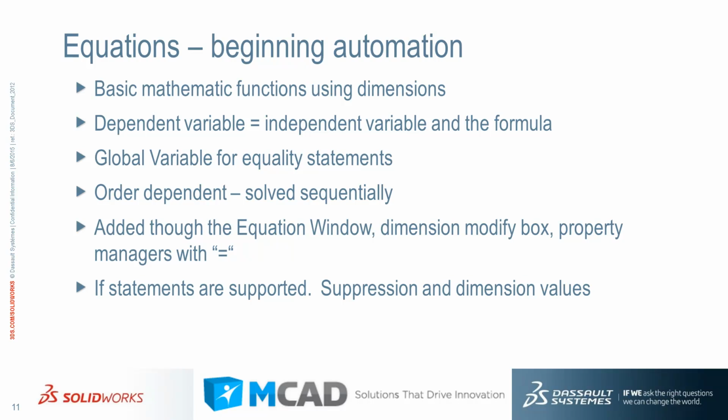And finally, if statements, Visual Basic if statements are supported. You can use them to drive suppressing a feature or different dimensional values a dimension is controlled by. So you can get some pretty interesting functions just using native SolidWorks equations. They, like configurations, have really come a long ways over the last few releases of SolidWorks.